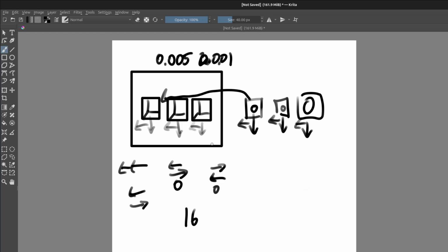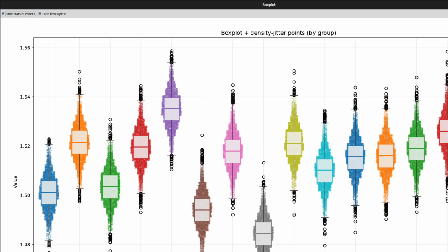So what you can do is cycle back over here. We have these distributions, and we cycle the actual cavity positions into different pockets. And then we do the same set of statistics on it. And you can separate out for each cavity, what is its shift? Is the shift 0.005? Is the shift 0.05 or 0.1? What's the shift of the pocket in the mold?